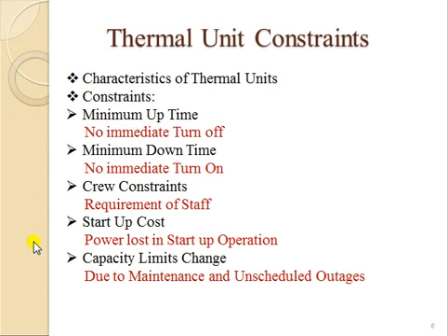So because of this time constraint, it cannot be started immediately, like you start the plant and it has started giving you power. The time is very important, so there are some constraints. Minimum uptime. So how to understand this minimum uptime? So just consider uptime. Here the unit has started. So after the unit has started, there is some minimum time before which you cannot turn off the unit. So this is a constraint. In a reverse way, if the unit is down, you cannot immediately start it. So this has a typical time constant for a thermal power plant, which is generally a slow response.